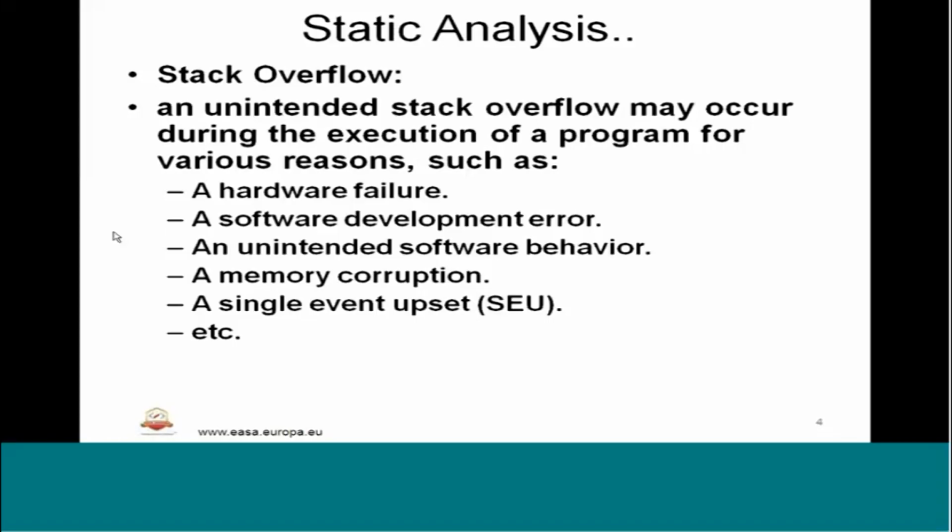An unintended software behavior, that means the software suddenly behaves unintendedly. Memory corruption, where memory is not written properly or the content of the memory is corrupted. And a single event upset, due to which stack overflow would have happened abruptly. Likewise we have different reasons for stack overflow. This needs to be analyzed.